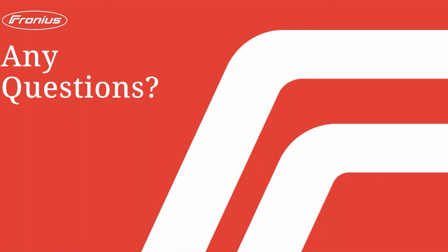The first one from Rowan is, how do you know when to use soft or hard limit? Yep. So I think we mentioned the soft limit is throttling back the inverter. The hard limit is switching off the device, basically turning the AC output off. So in the UK, we use the soft limit normally. Hard limit would only be required if there was a strict requirement. Maybe you're getting to the limit of the cable current carrying capacity, and you want to make sure that you have that protection in place.